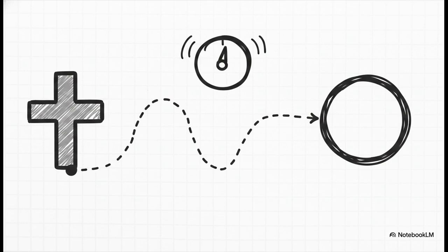And if you remember absolutely nothing else, remember this golden rule of the road. Every single branch on our map has a strict starting line and a finish line. The paths always start exactly at the open loop poles when our gain is at 0, and as we crank that gain dial up toward infinity, those paths travel across the graph to finish at the open loop zeros.